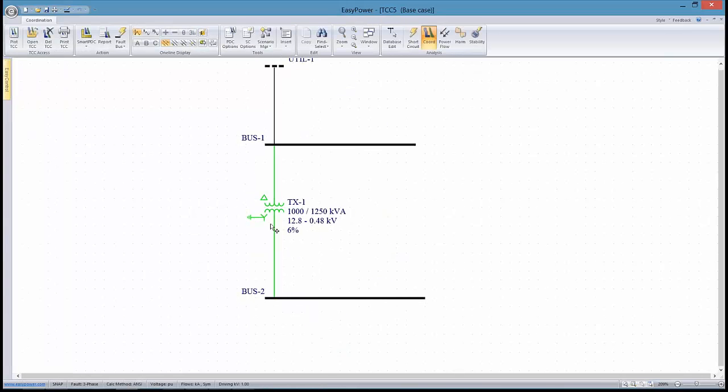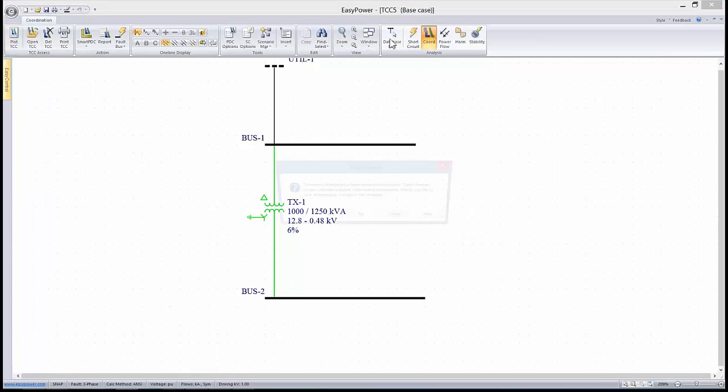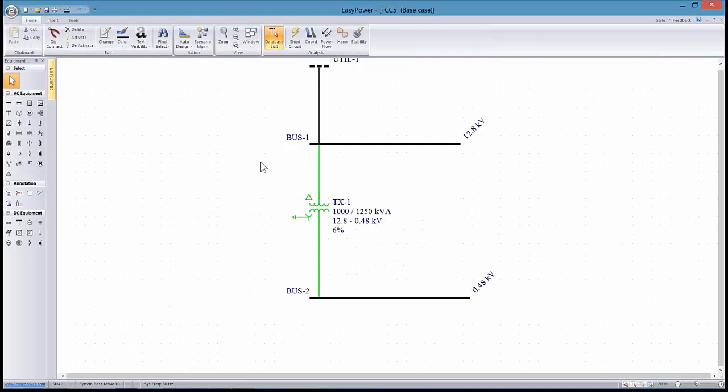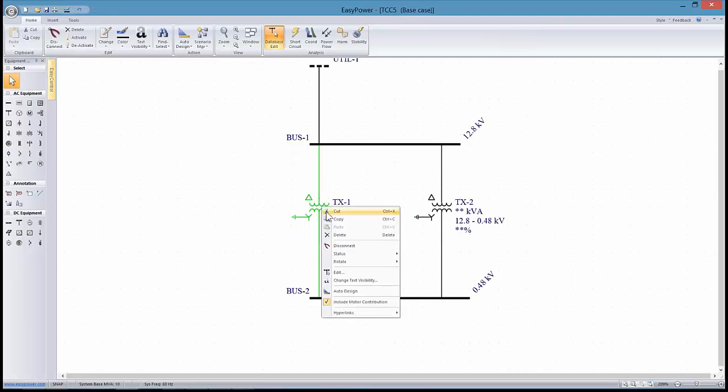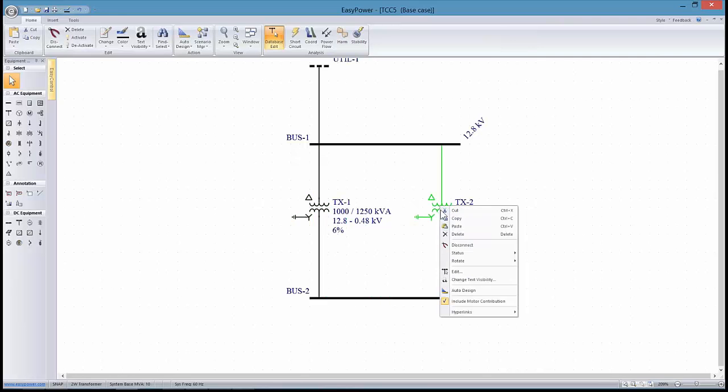All I have to do is get to the right example. So what I want to do is put the same transformer in play, and I need to do this in the database editor. Let's save the changes, put in another transformer. I'm going to copy and paste this transformer into the same place. Again, this is not the way you necessarily design things, but for purposes of demonstration.